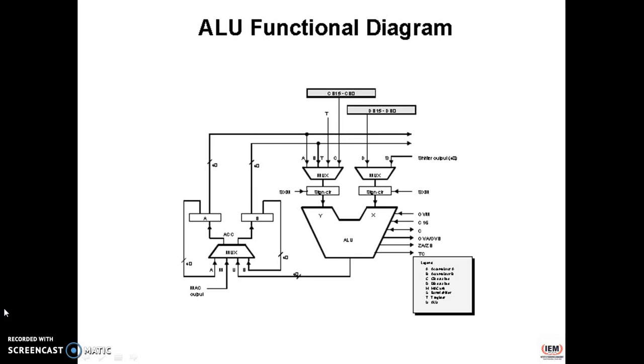Now we come to the arithmetic logical unit. The C54x performs 2's complement arithmetic with a 40-bit arithmetic logical unit and 2 40-bit accumulators. The accumulators are considered as A and B in the figure. The ALU can also perform Boolean operations.